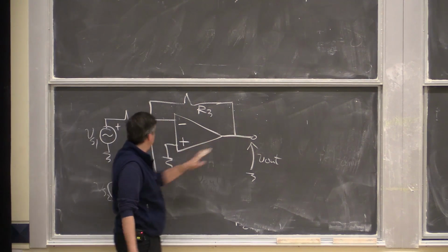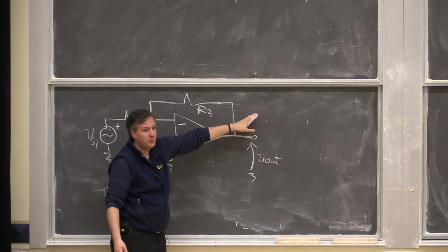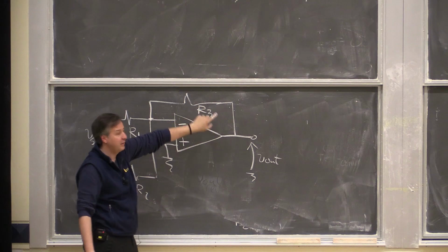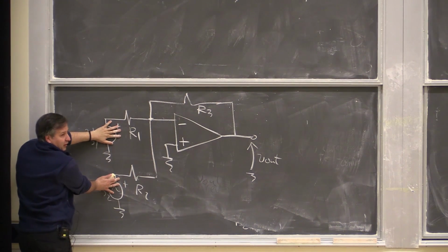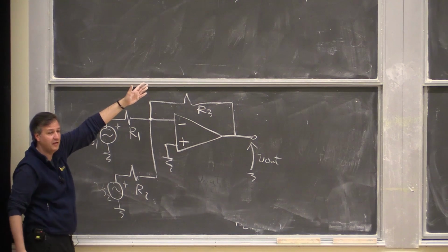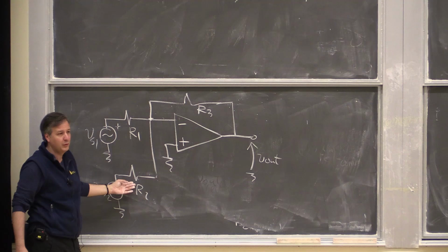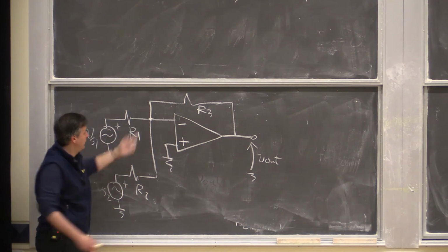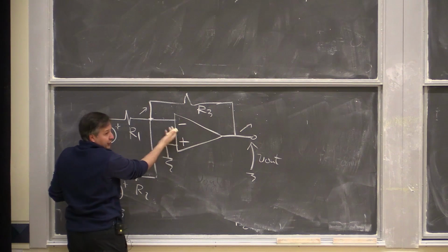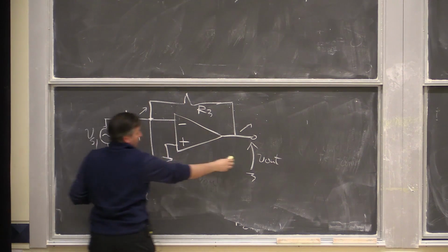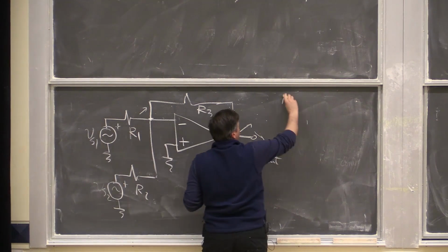The other one is, again, null the sources, increase the output, and then look in the feedback. So you get R. There's no current here. You just get two resistors in parallel to ground. It's a very similar thing to that divider. It's now a voltage divider between R3 and R1 in parallel with R2. Right? So again, if this goes up, this will go up. Again, you're squishing the negative terminal toward the positive, so this goes down. Okay, so this circuit is in negative feedback.